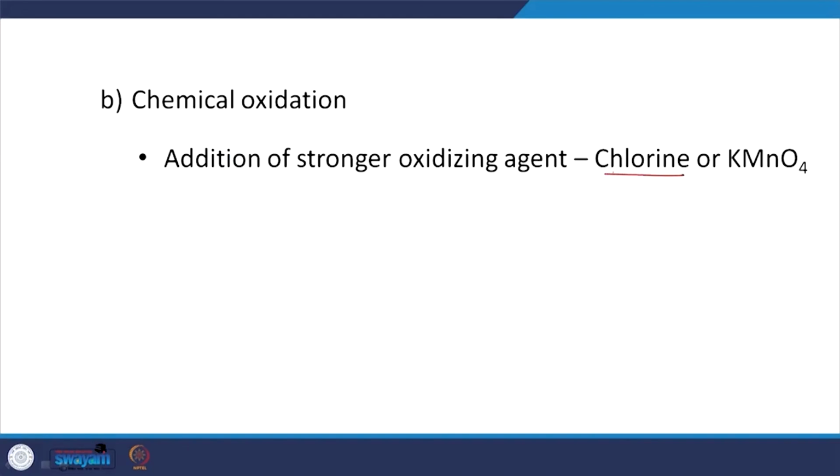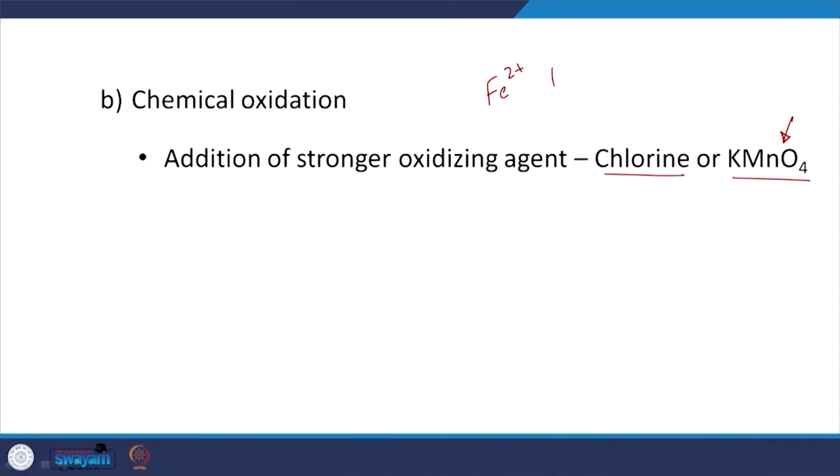So, chlorine, different forms of chlorine, KMnO4, but this is typically costly, and with respect to Mn2+, or if you have Fe2+ bound to natural organic matter, it is very difficult to remove it. We looked at aqueous complexes, right. Complexes, we need metal and ligand. Ligand examples, what did we look at? We looked at OH-, we looked at phosphates. And another ligand, electron rich, is NOM, which is a nuisance. As you can see, it also acts as a ligand and complexes with Fe2+, right. At least with Fe3+ it does form it.